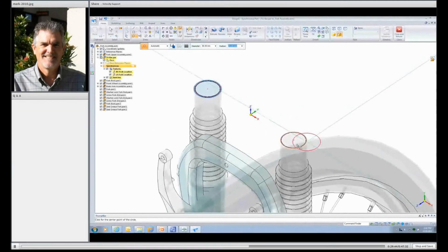And then if I want, I can turn off the background components. Now, of course, you can always go to View and turn off the background components, but you'll notice a Control Q will do the same thing. So I'm going to do a Control Q to turn off my background assembly components. I don't really need them at this point. And I'm going to turn off the base, and let's zoom in so you can see what I'm doing here.